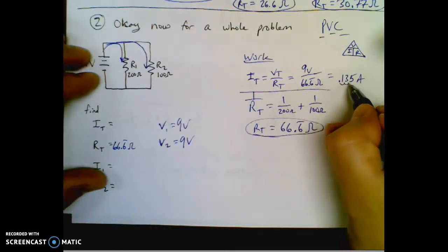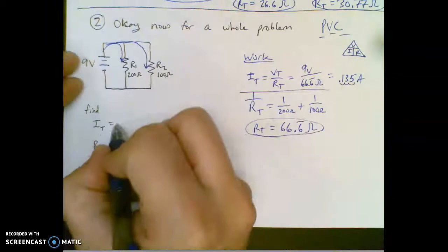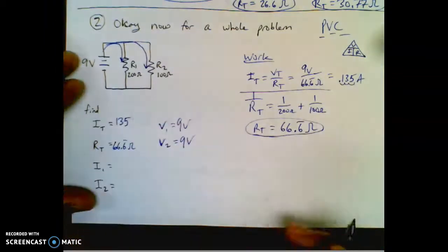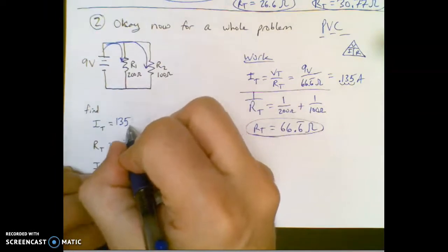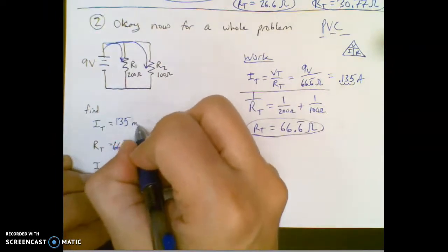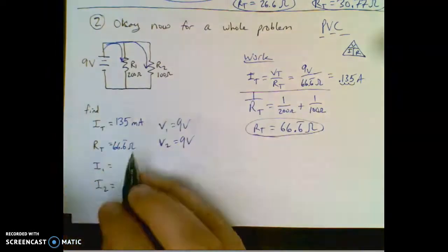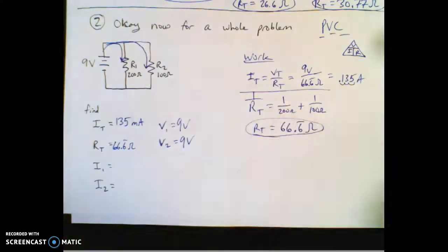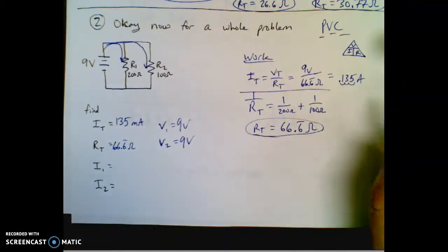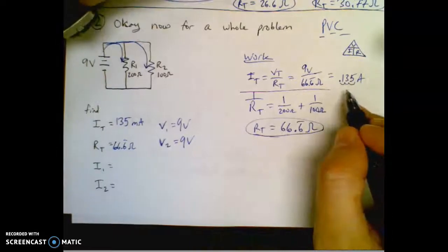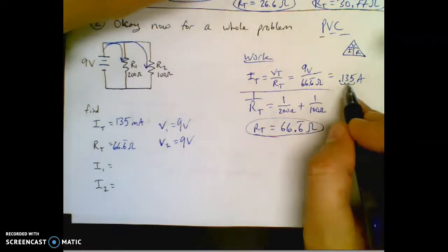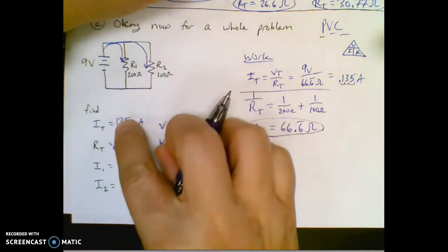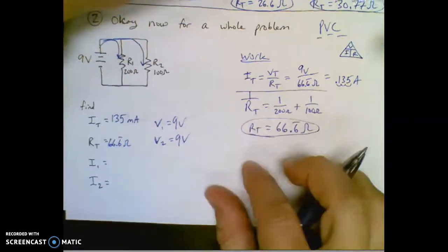So I'm going to move the decimal place over 3, and I get 135, and I got to remember that's little, so it's not micro, it's milliamps. So it's an M. If I would have moved it 6 places over and it's a tiny, tiny number, I would have done micro. But I do want to keep this answer for later, though. I want to keep the regular one. I don't want to use this in the formulas because you got to use regular ohms and amps.